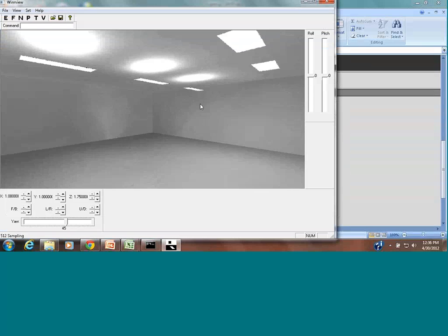So again, this is very critical in trying to find what fixture we're trying to use. And there's a reason why we want to go through this exercise. Because during the nighttime, the light fixture design should provide adequate design illuminance without any help from the daylight. So the light fixture design is critical for that. So going through this with your electrical engineer is very, very important.